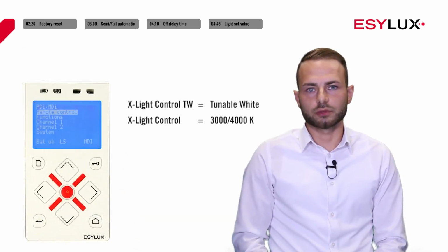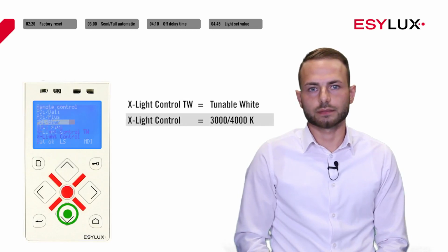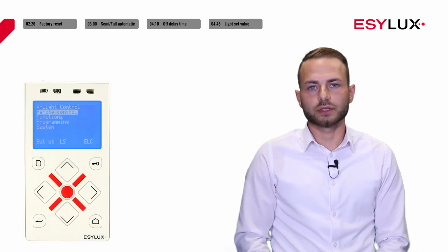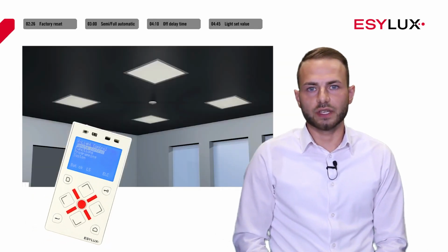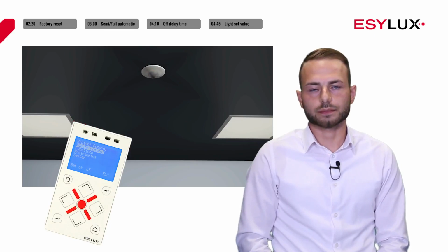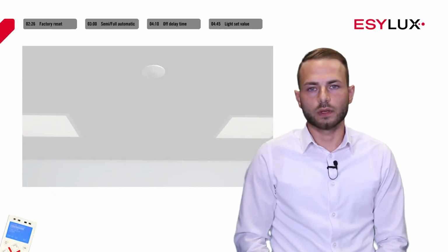Ensure that you have activated the correct remote control menu. Point the remote control towards the presence detector. If you send commands, the LEDs in the presence detector acknowledge that these commands have been received.